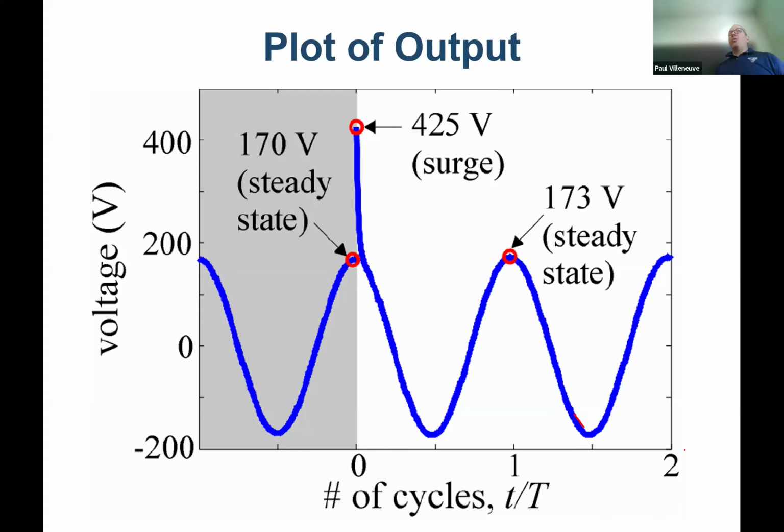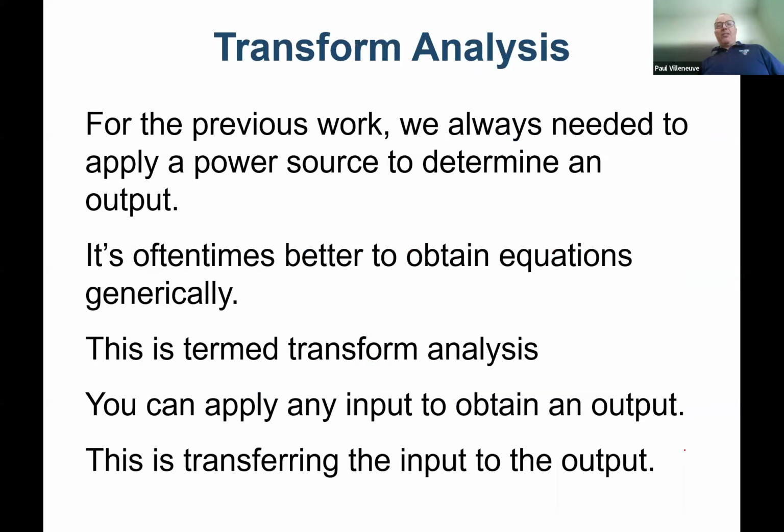And so if you were to go to Orrington, they have 2 series cap banks, and they can take those out of service. What they do is they actually have a path around the cap bank that has essentially a Zener diode that protects it. So when you open up the breakers, and the voltage tries to spike for one reason or another, it will just discharge the capacitor slowly. So you have to add a higher level of sophistication.